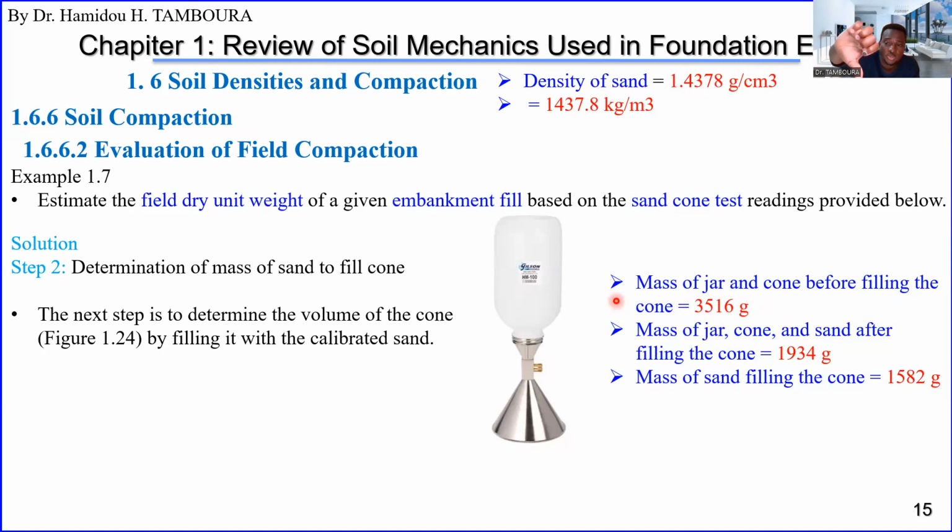Then now you put it in this way, like this, and you open the van, the sand will go down here until it stops running. Once it stops running, it means the cone is full, right?